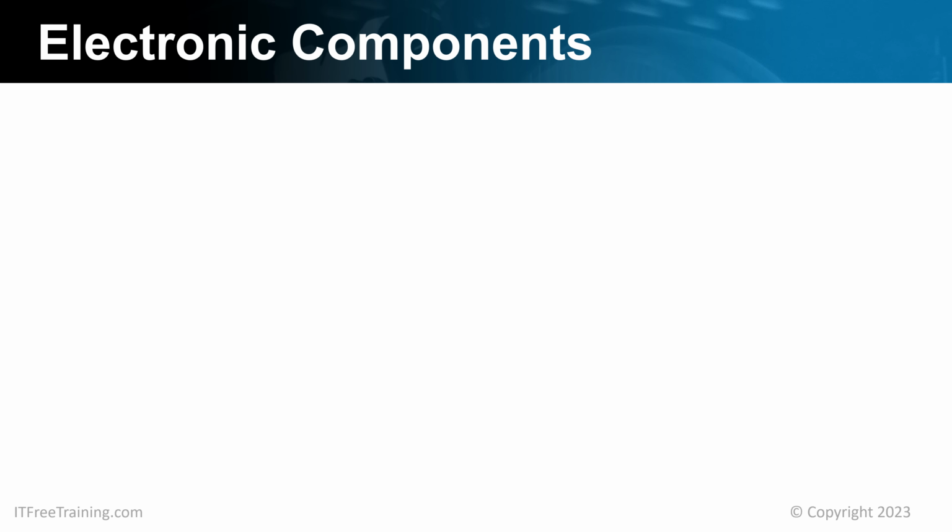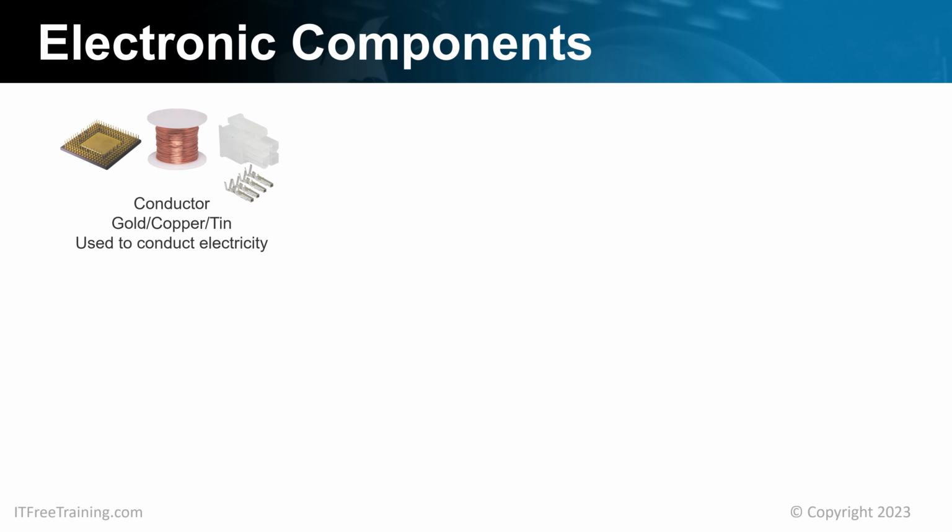The first component I will look at is conductors. As the name suggests, these materials conduct electricity. Different metals are better at conducting electricity than others. For data wires, particularly high-speed data wires, you may find that the pins of the connector are gold-plated. The gold plating generally ranges from 1/4 of a micron to 5 microns in thickness.